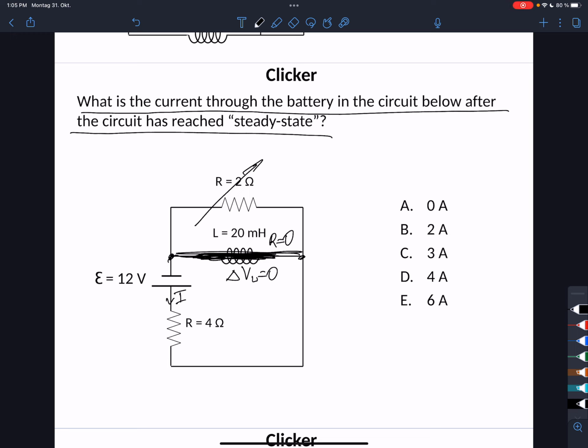Consider that the resistance is 0 and compute what would be the current through that part and what would be the current through this part. Here you obtain that the current is 0. There will be nothing flowing through this resistor, and here the current will be I. It's also the rule that if it is short-circuited, the current flows only through the wire, not through the resistor. But again, you can compute it.